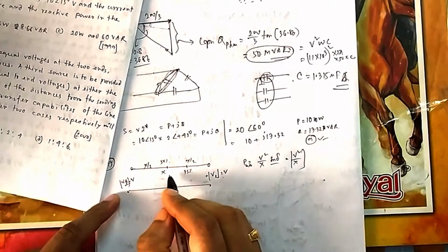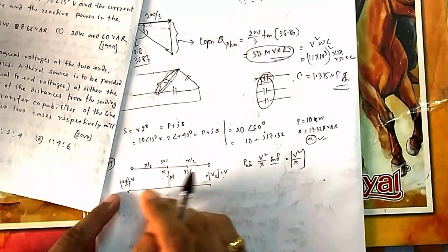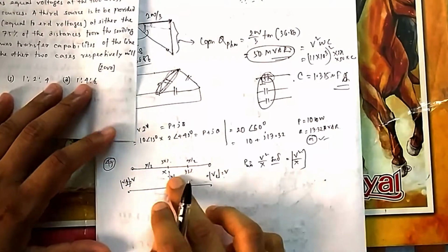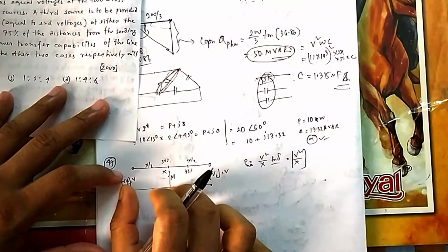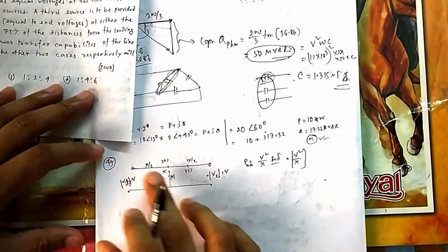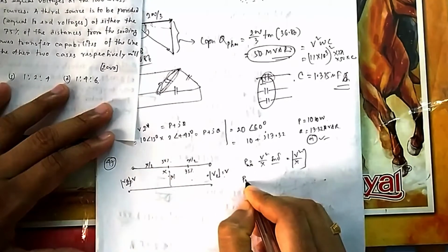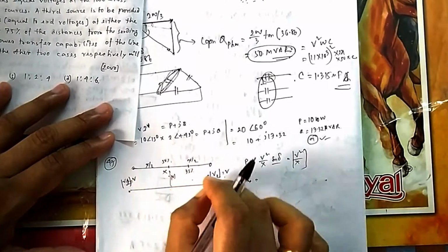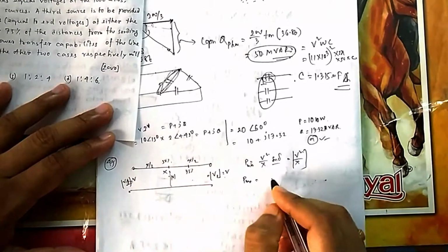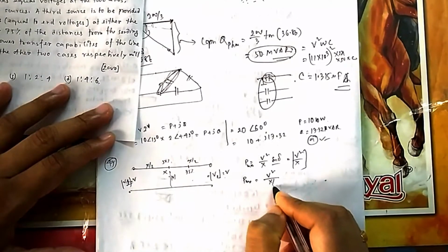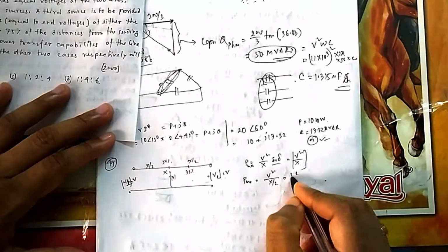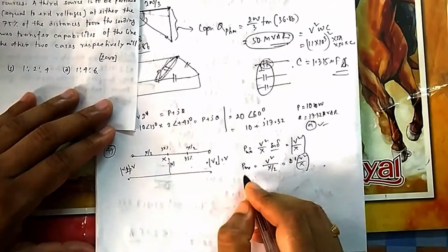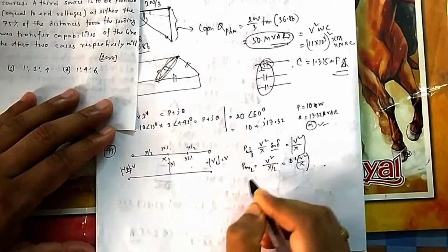So whatever power here, the voltage magnitude is also V. So whatever power you have from here, it can be transferred to here, the same power you can think of. Let me see how much power I can transmit to here and how much power I can transmit to here. Both will be the same because both are X by 2. So here P max, you can take either this X or this X, same power. Whatever you transfer here, the same amount you can transfer this side also, because it is X by 2. So it will be V square by X by 2, or 2 V square by X. That is twice the first one.